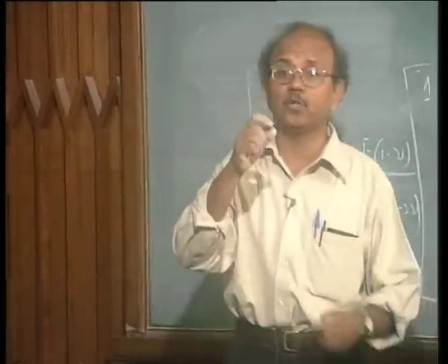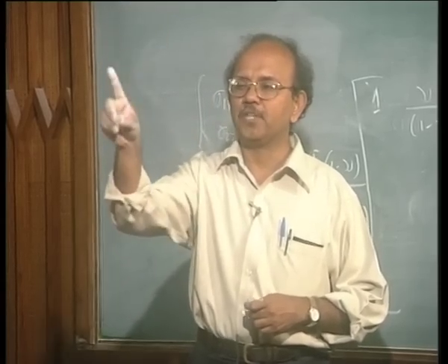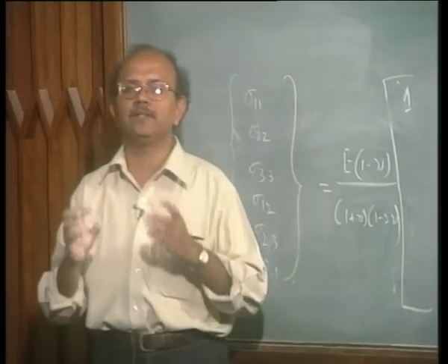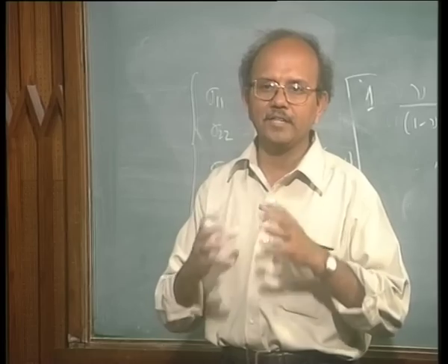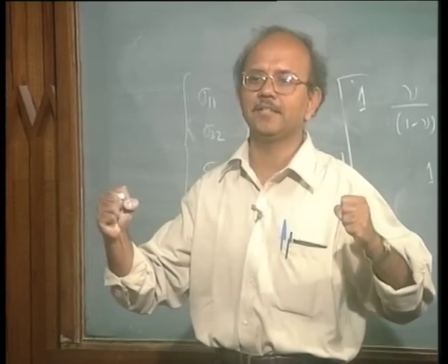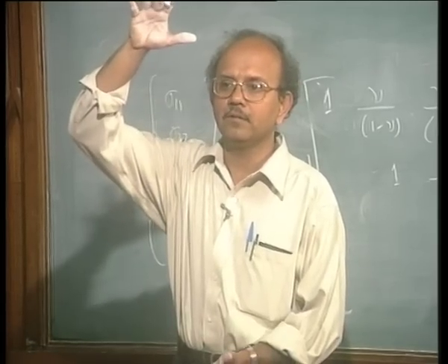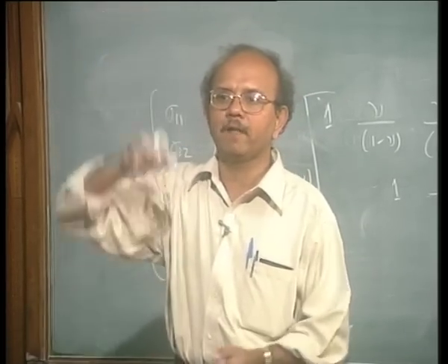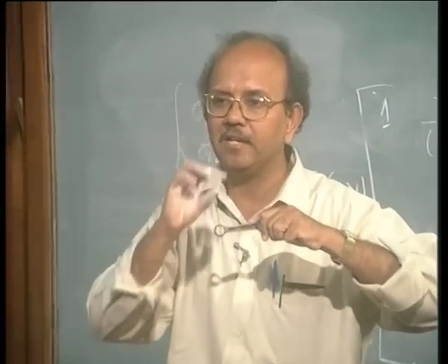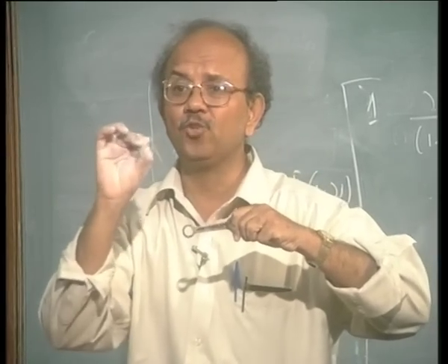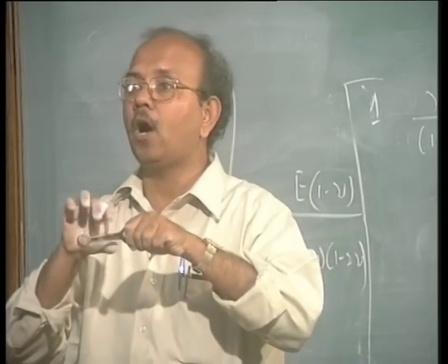Please note this carefully. When nu is minus, look at the way I defined it. There are certain forms which have been discovered recently, manipulated such that when you take this form and apply stress, instead of the other side coming in, the other side would start going out. When I pull a bar, the other sides would start coming in, and then I defined nu to be positive. On the other hand, when I pull the bar, these sides start going out.